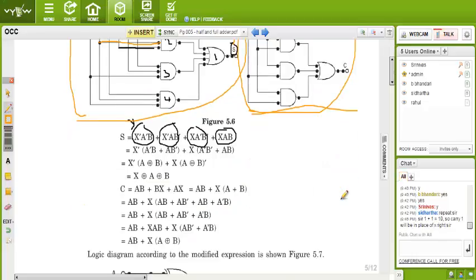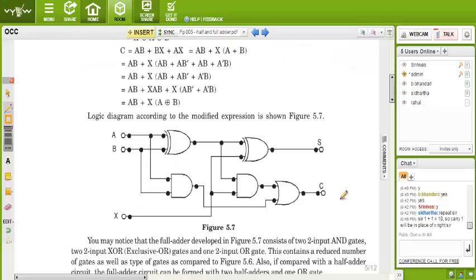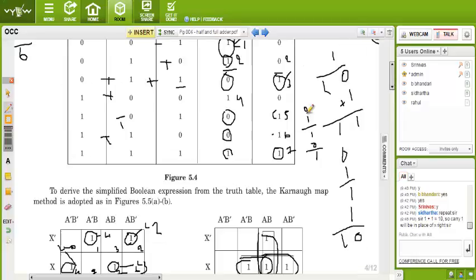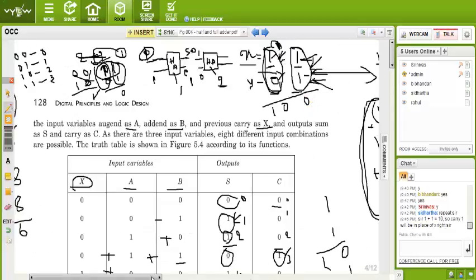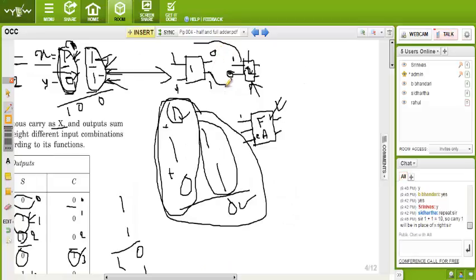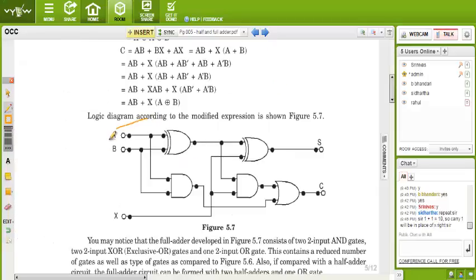Two separate ones, okay. Now see, there is another process. We can easily make the full adder circuit by adding two half adder circuits. By using two half adders, if there is a provision to add a carry or get an extra input, we can create a full adder. So here it is a half adder circuit, and here again a half adder circuit.